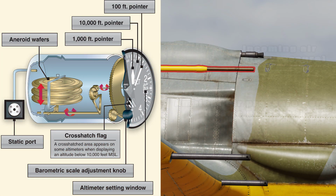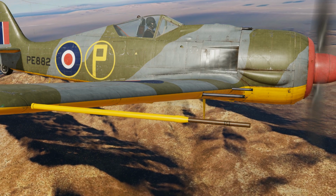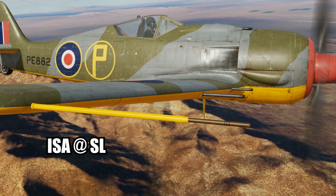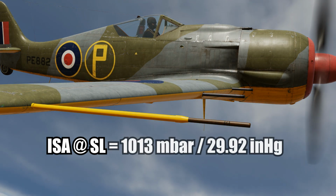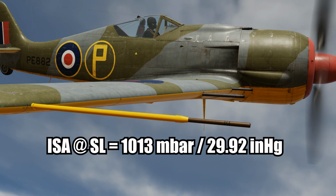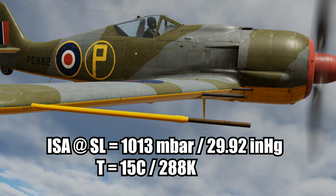To understand why some types of errors appear, or why some corrections need to be applied, you first need to learn that all the pneumatic instruments, in all aircraft, are calibrated using the International Standard Atmosphere. This is a mass of air that has a sea level pressure of 1013 millibars, or 29.92 inches of mercury, and a temperature of 15 degrees Celsius.